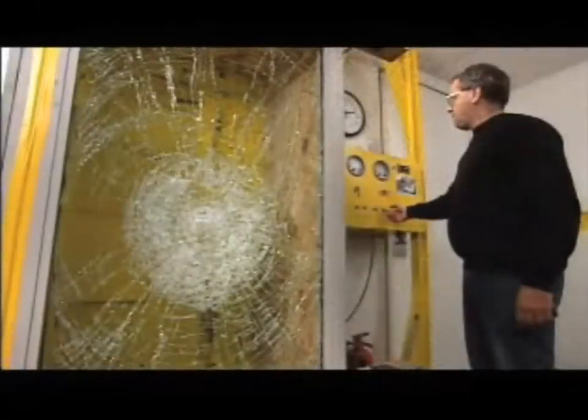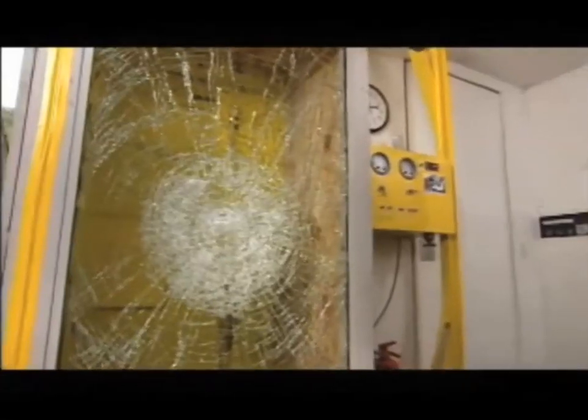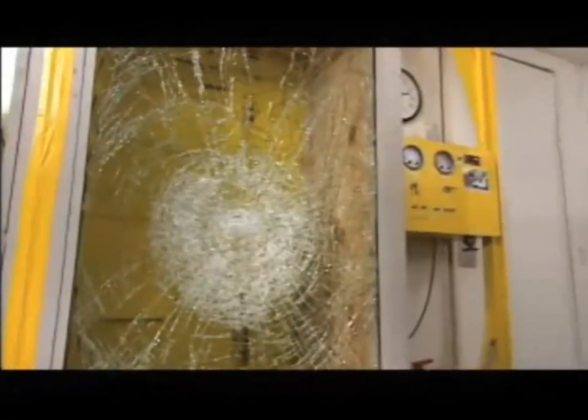And because during these storms the windows may be subjected to sustained, gusting winds, both sides of impacted glass units are put through cycling tests that simulate winds up to 180 miles per hour. Cardinal also tests the security application of laminated glass for resistance to forced entry, and laminated glass cannot be cut from one side only, rendering glass cutters useless.